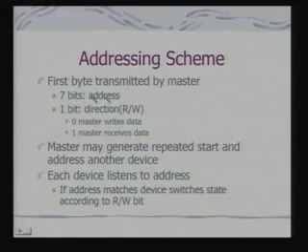So, this is the basic addressing scheme. There are 7 bits which is used for addressing the slave devices. So, each slave device can have a 7-bit address. The 8th bit is basically the direction which tells you whether it is a write or read.